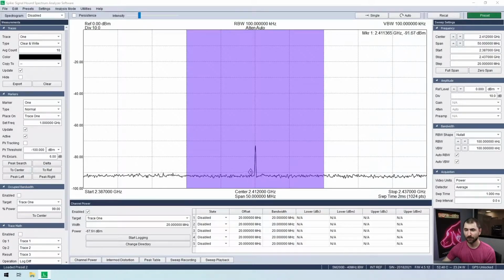In an over-the-air measurement, the signal of interest may be part of a protocol which transmits short packets or bursts of energy, making it hard to reliably measure channel power with this method. For this, we can utilize the zero-span method of calculating channel power.